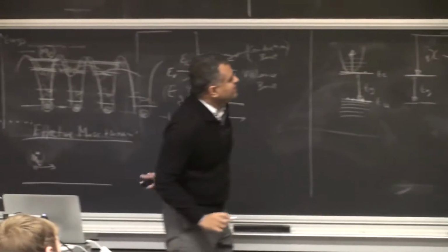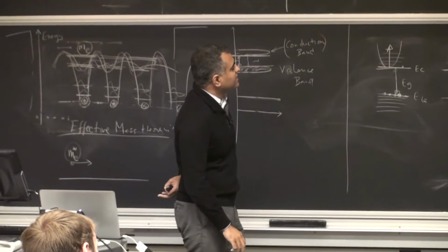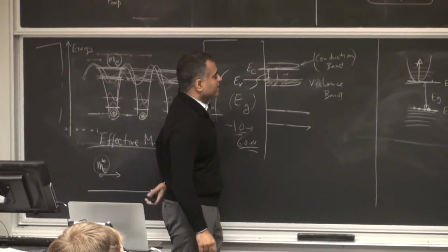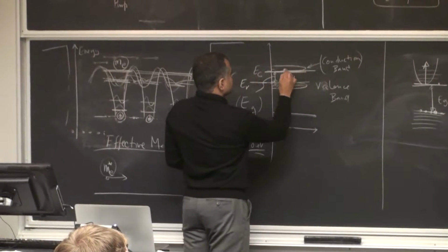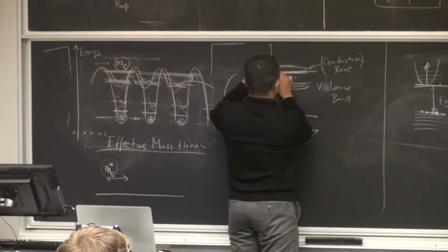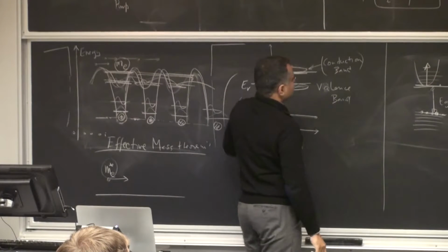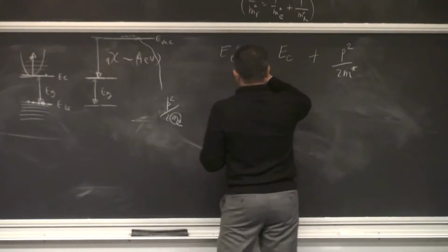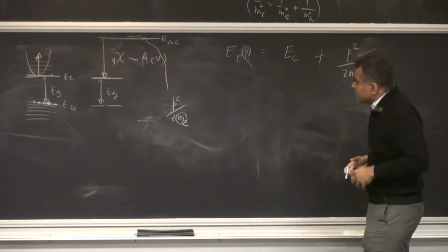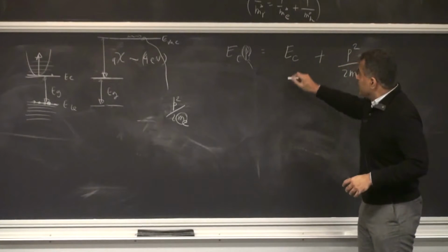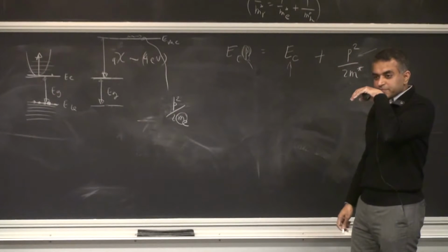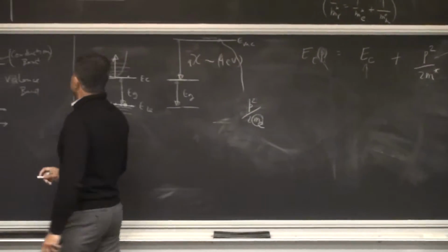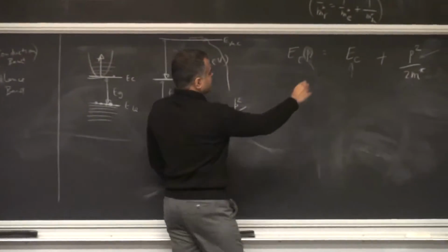So E_C, is that the potential, so is that like the energy of the lowest band? Is that supposed to be the total energy? So it's the conduction band? The conduction band here is going to form a manifold of various energies, and if you are at the bottom of that manifold, the way you climb in that manifold to higher energies is using momentum. So you have kinetic energy as it moves, and this is the minimum. So the left is describing an energy within the conduction band. It's confusing because there are two E_Cs. Right. Okay, so that's a good point.